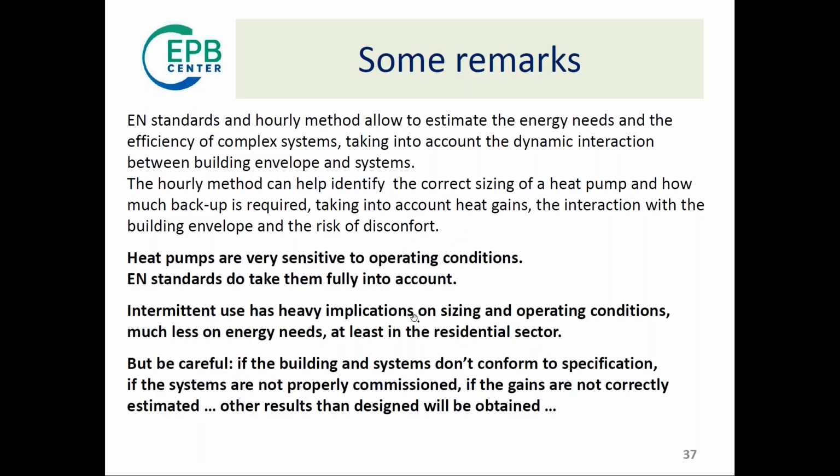And it's the hourly method that allows to take into account the heat gains and the interaction with the building envelope and the risk of discomfort. And that's quite important to have hourly method when you deal with very sensitive devices like heat pumps, which are quite sensitive to operating condition. And EN standards do take this fully into account.